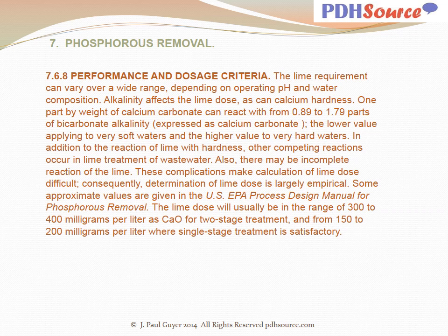In addition to the reaction of lime with hardness, other competing reactions occur in lime treatment of wastewater. Also, there may be incomplete reaction of the lime. These complications make calculation of lime dose difficult. Consequently, determination of lime dose is largely empirical. Some approximate values are given in the U.S. EPA Process Design Manual for phosphorus removal.